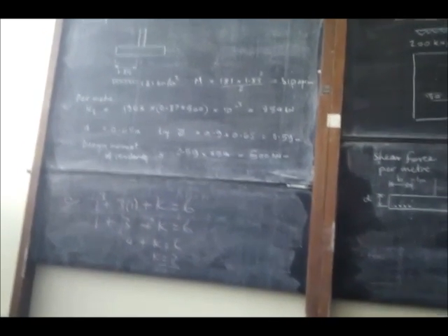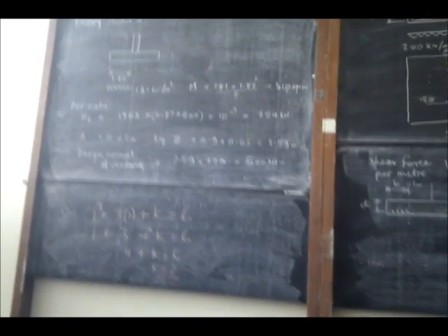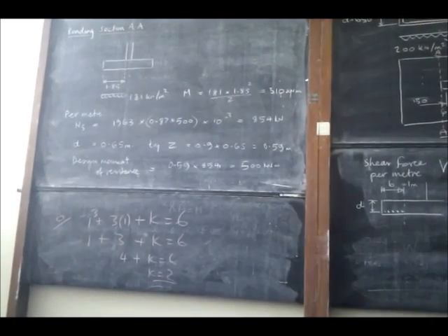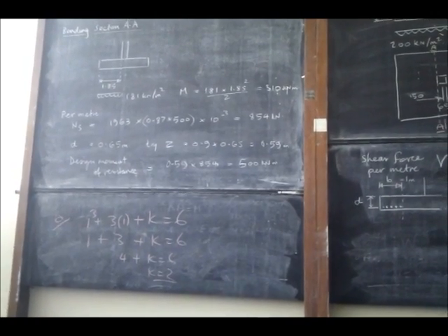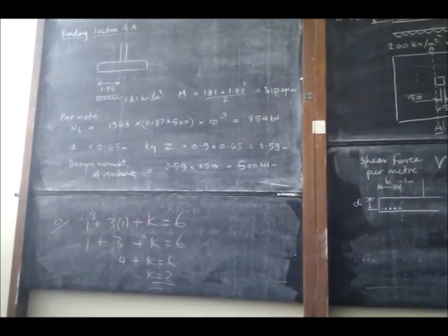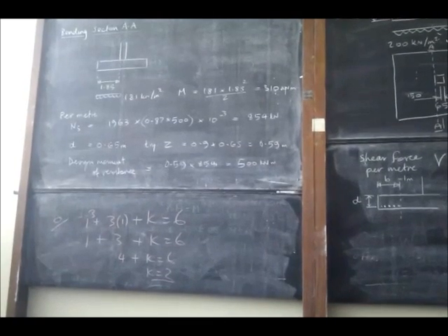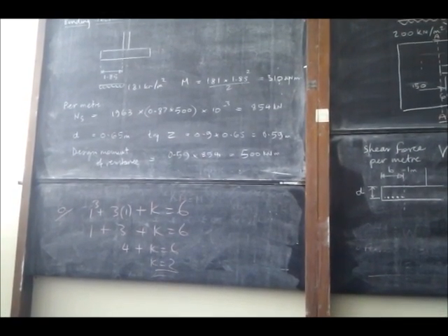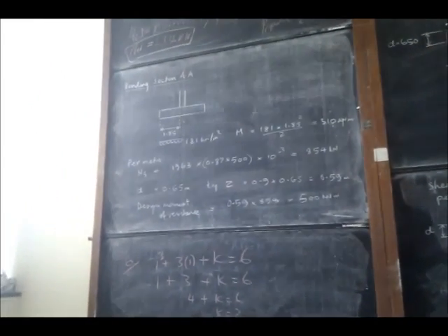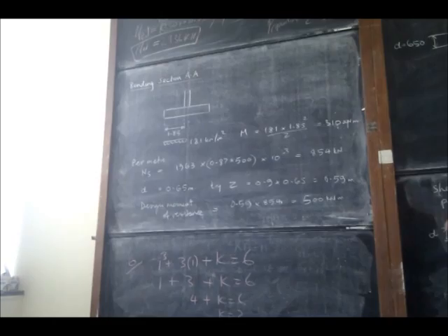You can use the formula for K to check the ultimate moment, the maximum moment that a single reinforced section can take. And then you can use the formula for Z. You get an exact value for Z, and you'll get a more precise answer. But given that the answer that we've got here is 160% times the value we need, that's close enough.